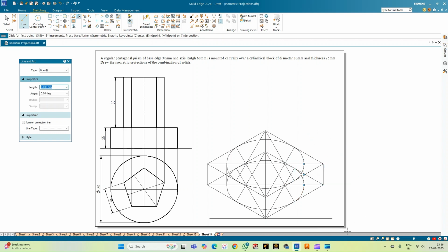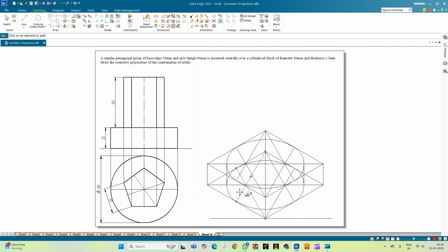Now whichever is visible to the observer, let us just darken that. Anyways, the bottom circle, this arc is visible. Since you can just see that this is a continuous arc, let me use the split option here. Let me select this entire arc first and split the arc at this point. There's a split command beneath the extend to next.